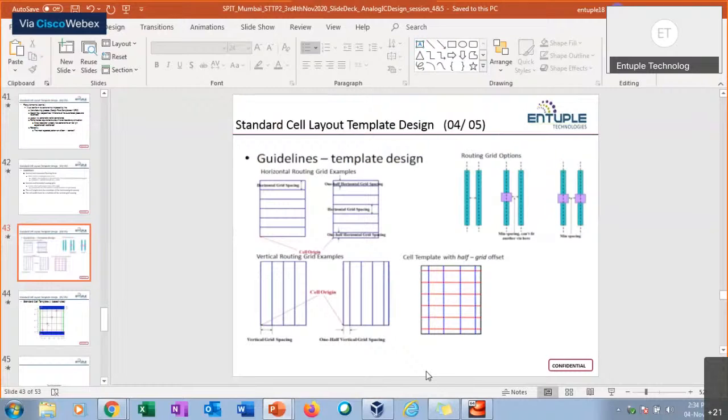Through that we obtained the ratio of mobility, and then we measured the width of the PMOS transistors. Then we created a schematic symbol and generated a test circuit. We created our own test circuit and executed the simulation. We did a transient analysis and a DC analysis.